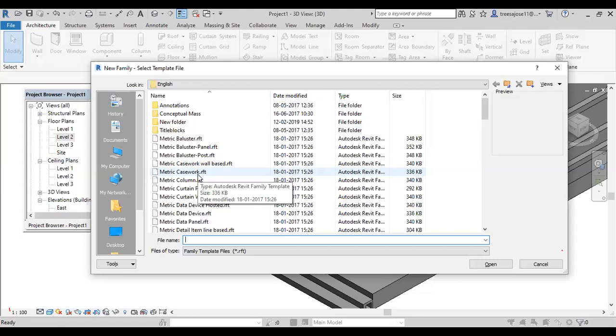I think it is better you use Save As, because if you save that, the parent file will be updated. Whatever file you select, make the changes, then save as an RFA file, then you can import that one also. Here these are the families of RFA files available.